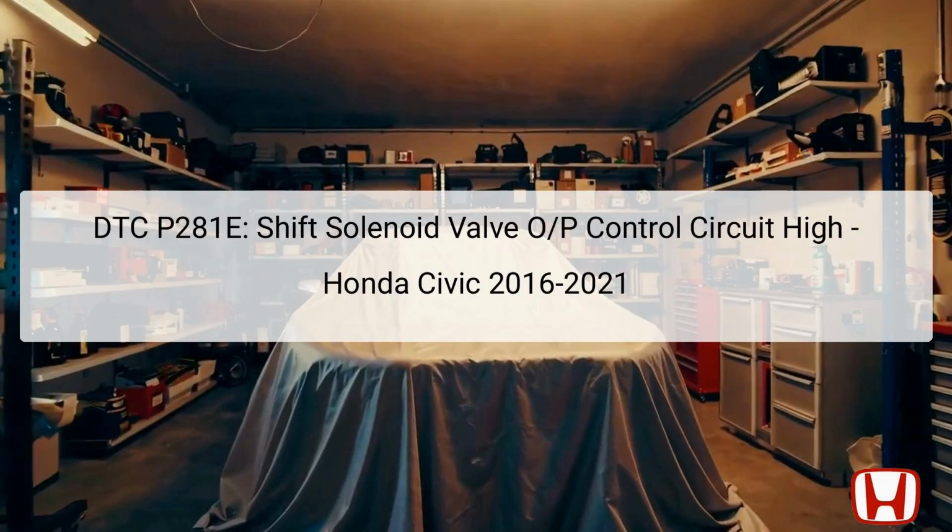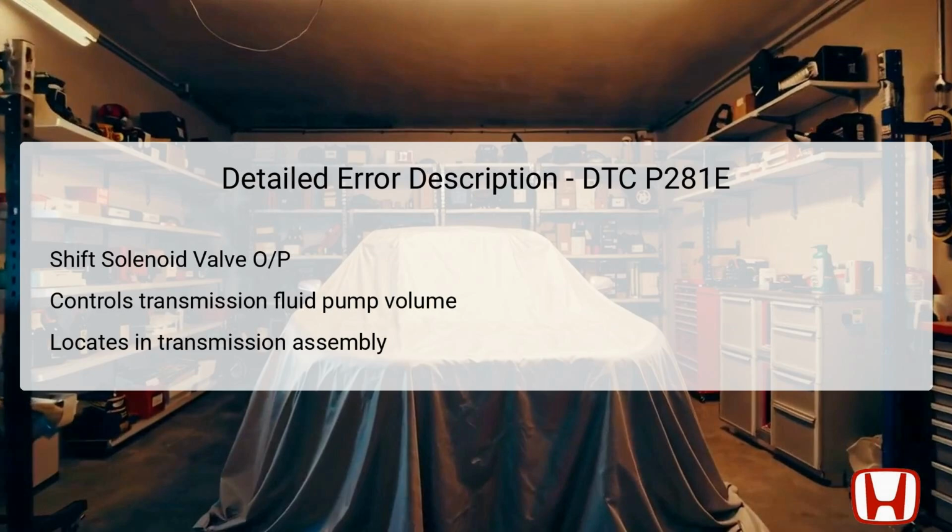Understanding the components involved, such as the shift solenoid valve and TCM, is central to diagnosing this problem. The TCM is crucial as it manages commands to the shift solenoid and assesses feedback from the system to ensure proper functioning. DTC P281E relates primarily to the Shift Solenoid Valve OP, a key component within the Honda Civic's transmission system.